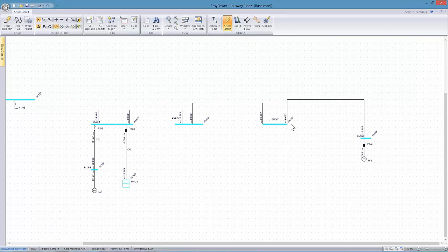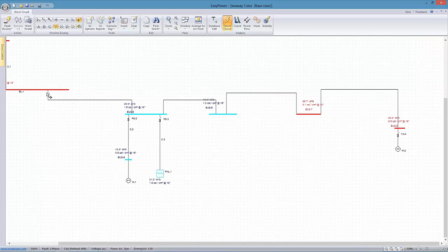And then it gradually reduces. The significance of that is when we go in and calculate incident energy, it's going to gradually build up because a fault at this drop point, even if it's averaged, is going to be protected by the settings on this particular breaker if we have no other inline protective devices.